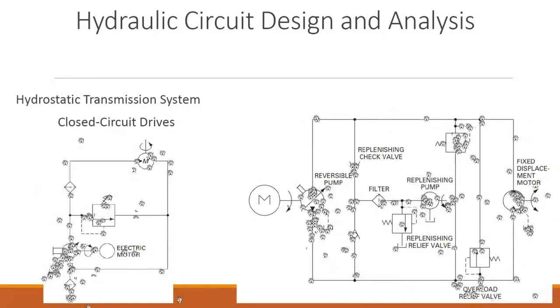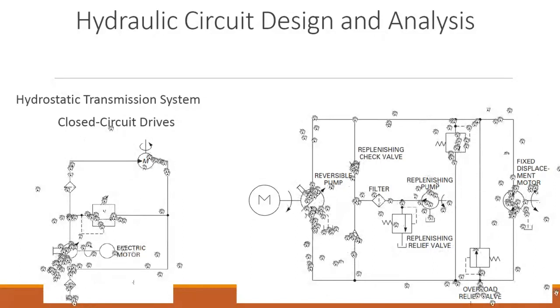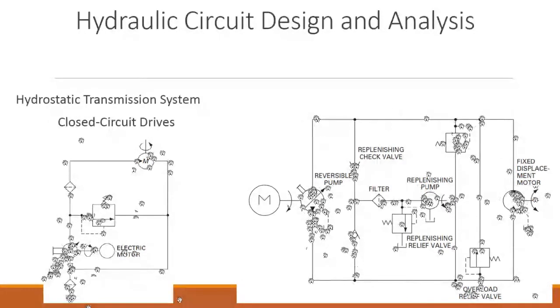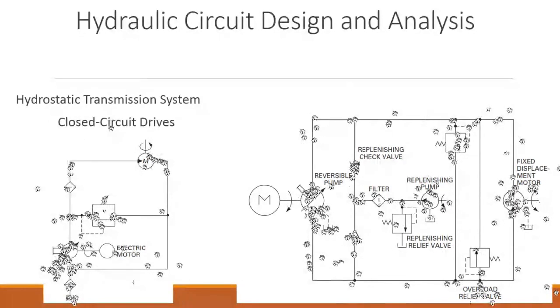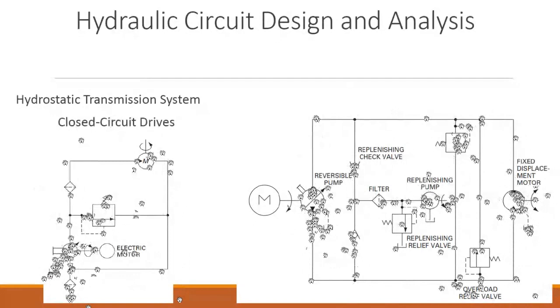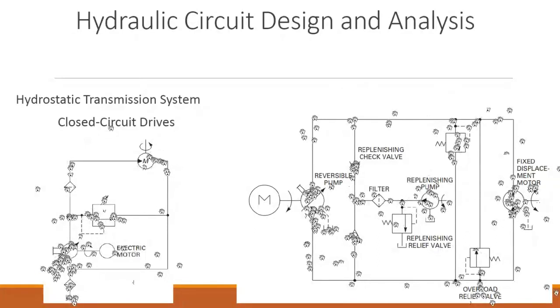Since this is the high pressure side, it will not open because the oil is just pressing this one against its seat. So the oil will come here, push this one because it's the low pressure side, come here and then join the mainstream oil and continue flowing in the main pipeline, actually covering the lost or leaked oil.